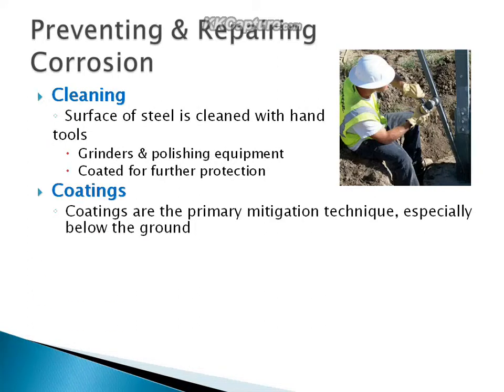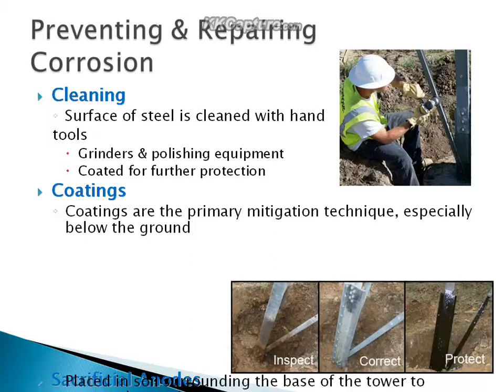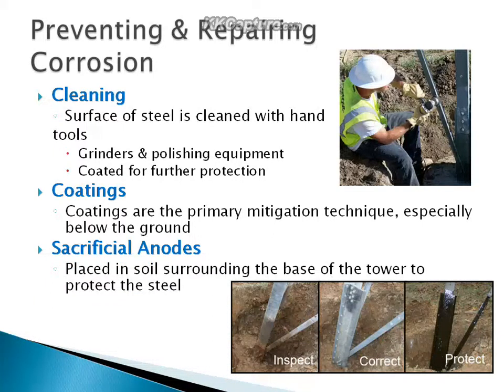In addition, sacrificial anodes are used at the base of the towers to prevent the corrosion of steel. These anodes also require monitoring, as they must be replaced regularly in order to continue protecting the steel. There is also a grounding path on all electrical towers to direct lightning strikes to the ground and prevent high electrical surges in the structure of the tower.